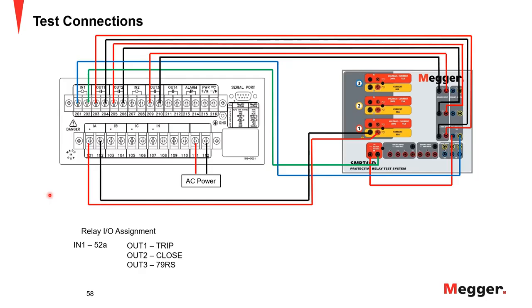Thanks. So while we have you, what is the difference between reclose and restrike? Reclose is when the reclosing relay tells the breaker or recloser to go closed, and it actually goes closed. If the fault is clear, then it's a successful reclose. If it is not clear, upon closing, upon a successful reclose of that breaker or recloser, the fault can restrike. So the difference in a reclose and a restrike: the reclose is talking about the breaker or recloser and the action that it's taking. The restrike is whether or not the arc actually reestablishes, whether the fault comes back.